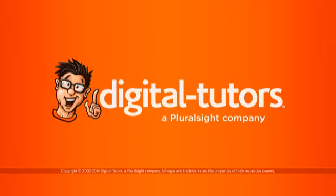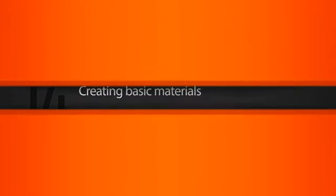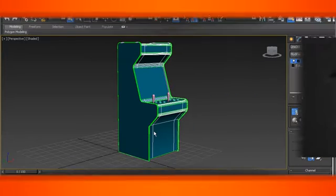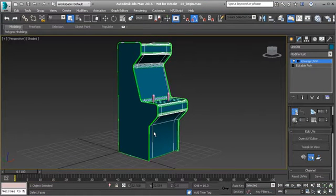In this lesson, we're going to learn how to use materials inside of 3ds Max. Alright, so now that we have unwrapped our model, we've taken that UV template, we brought it into Photoshop, we created a very quick texture. Now what we want to do is learn how to apply that to the 3D model again. So to do this, let's go ahead and open up our material editor.